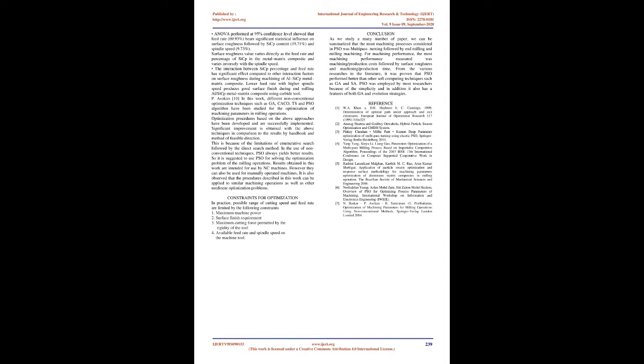Significant improvement is obtained with the above techniques in comparison with the results by handbook and method of feasible direction. This is because of the limitations of enumerative search followed by the direct search method. In the use of non-conventional techniques, the memetic algorithm always yields better results. So it is suggested to use the memetic algorithm for solving the optimization problem of milling operations.